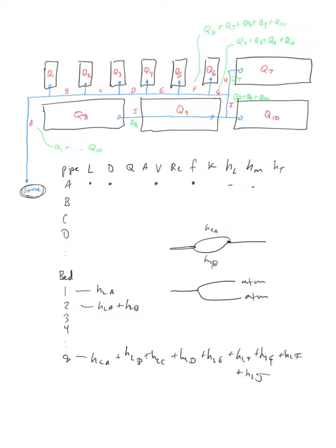So the head loss through each branch here has to be the same, right? We have one value of head here and one value of head here that's the same as the value of head here. And so the flow is going to split in order to make sure that the head loss in the top branch is equal to the head loss in the bottom branch.